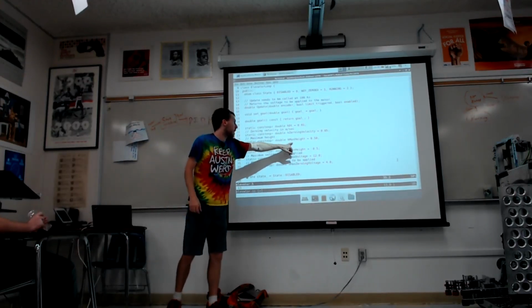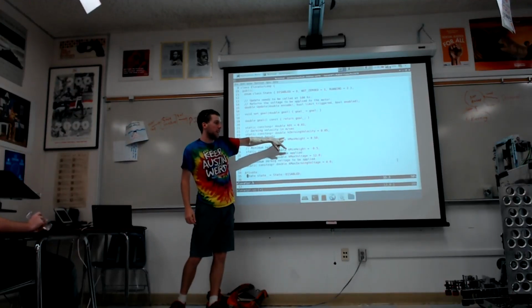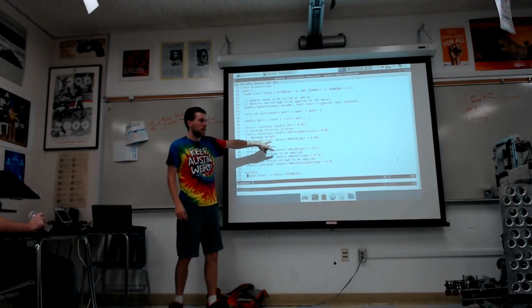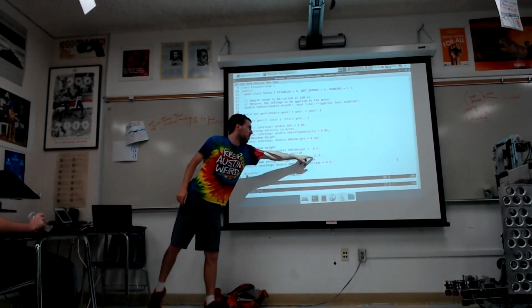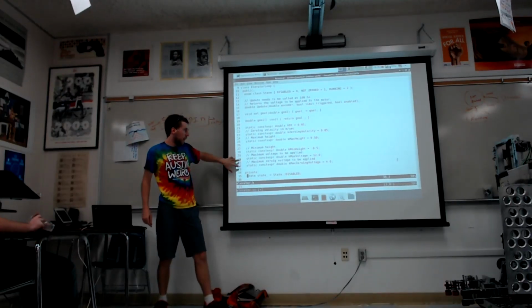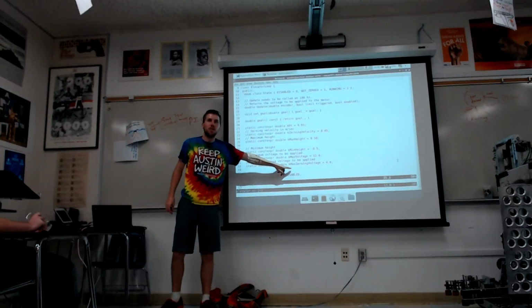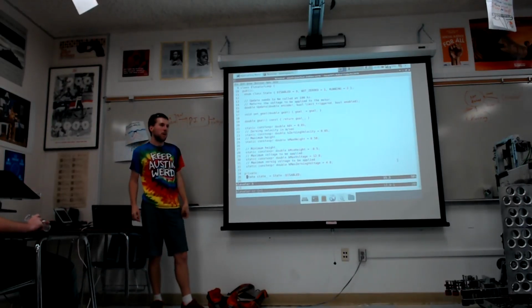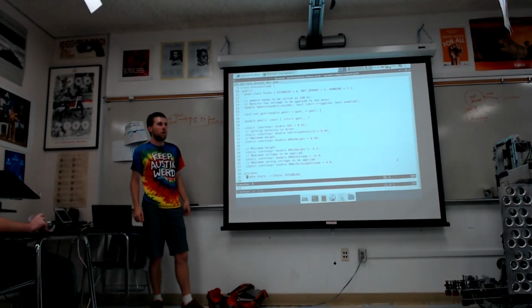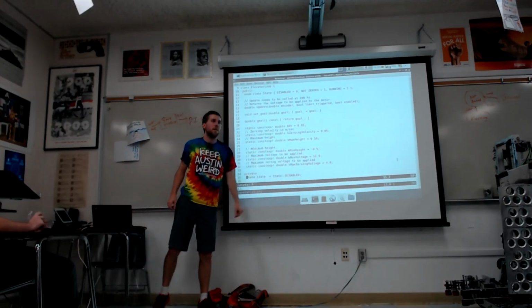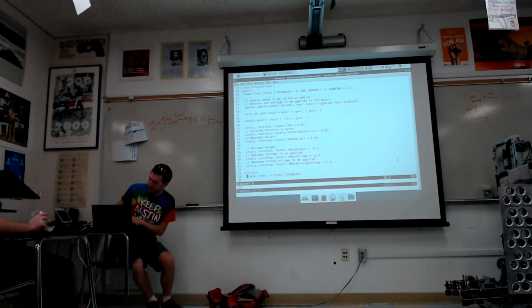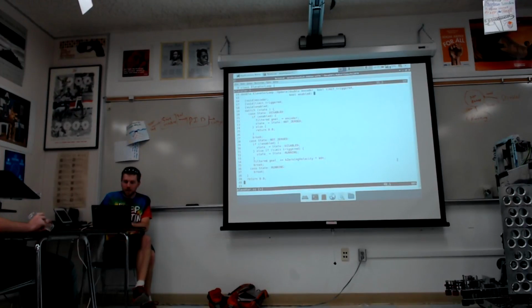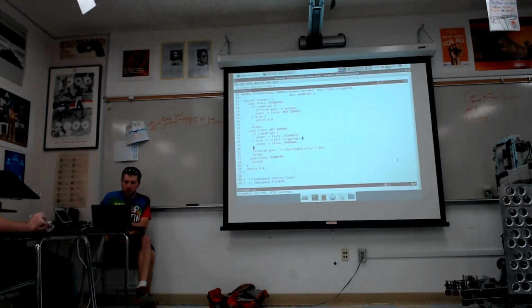And then the other ones are max height and min height. I think these are a little conservative on this hardware, but we don't need to push the limits. These tell us how high up and how far down we can go. And then max voltage is the max voltage we can apply. I firmly believe that when you don't know where you are, you shouldn't apply full voltage. So we have a separate constant for how much voltage we should apply while we're zeroing. So when we turn it on the first time, I don't want to give it all of the power. I'm kind of scared. So we're going to turn it on very carefully and slowly. Does that help? Awesome. Okay, so we've got a filtered goal. So let's write a little PID loop.